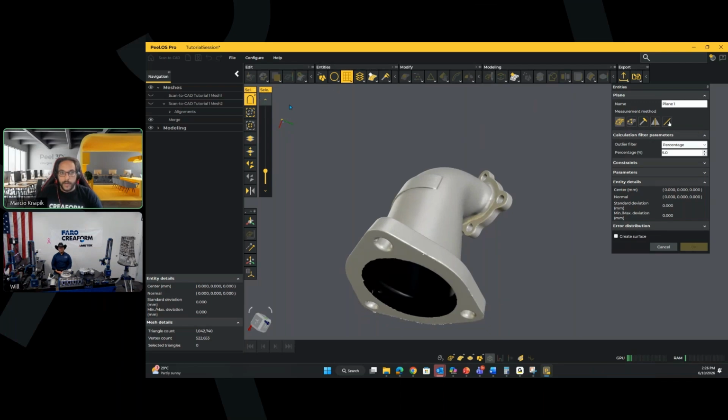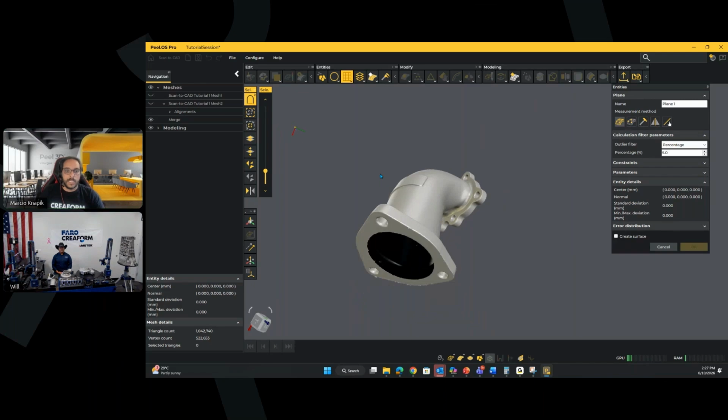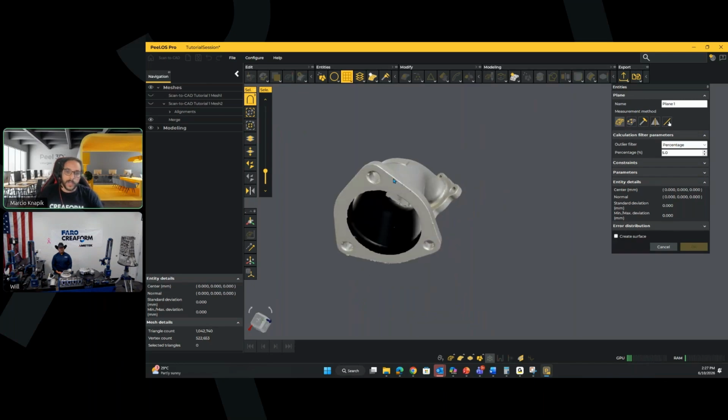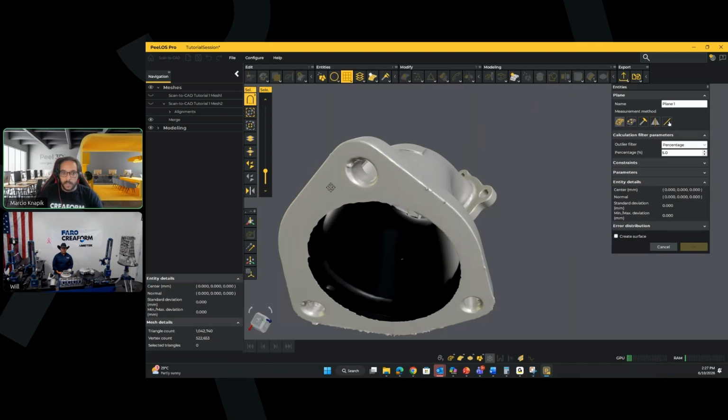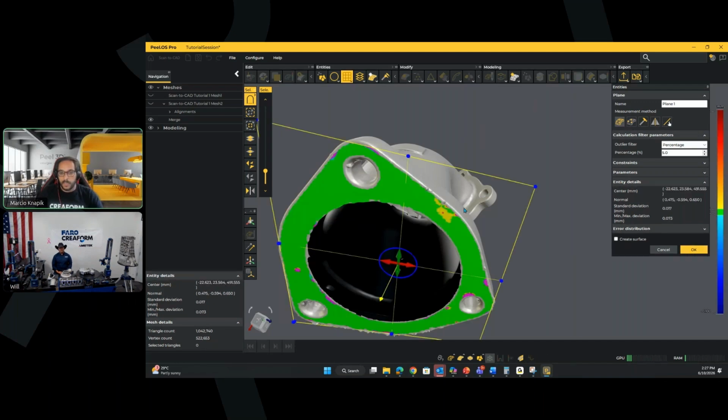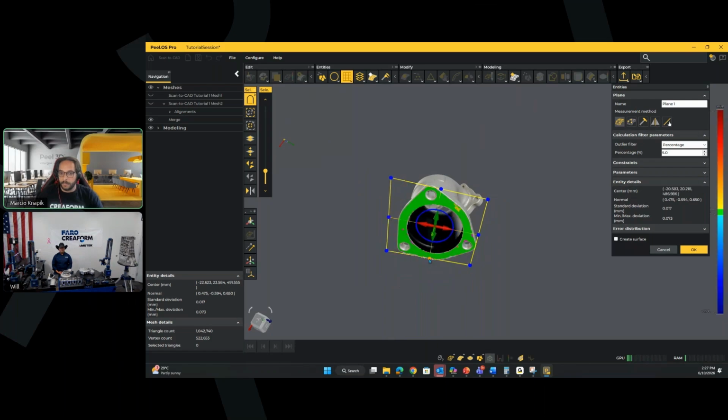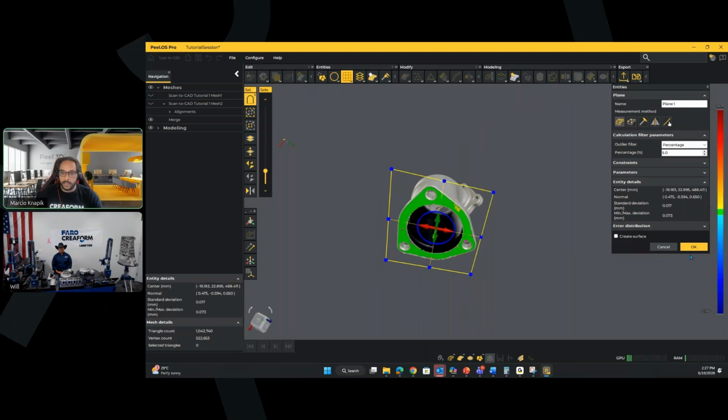And then when you select the plane, the software will understand that you want to select a plane, and the software will automatically switch the selection to manual similar normal. Sorry. So all the triangles pointing in the same direction will be selected, and then it's just one click, and the software will best fit a plane. So I can drag and drop to extend the planes, but yeah, it's just click OK.